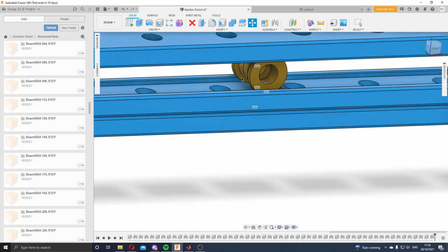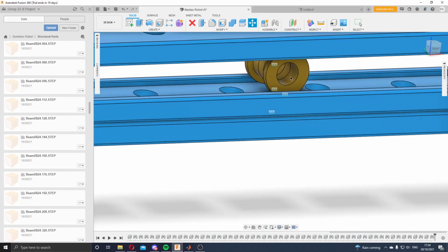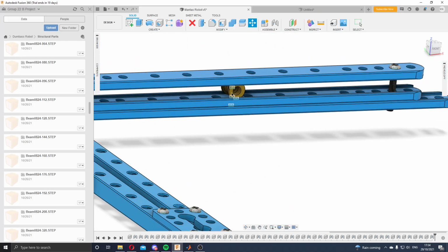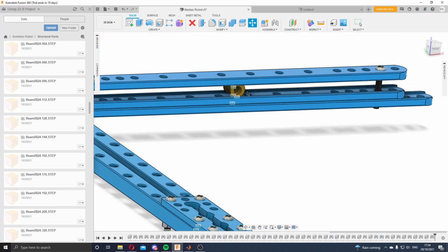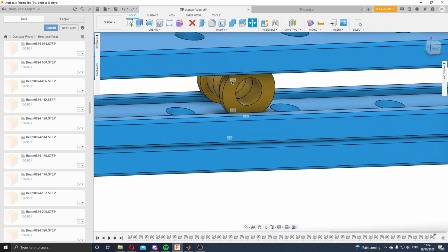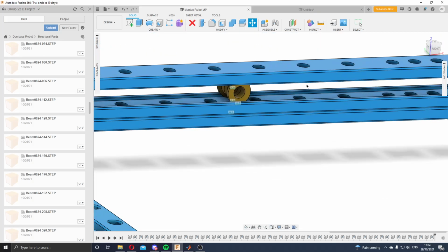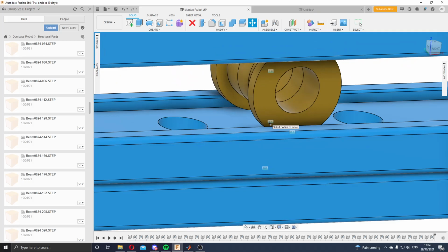If you don't want it to do that, there are these little things here, which allows you to select which bodies you are gonna move. So you can actually detach these bodies, for example. So in my design here, I have a little roller wheel that moves left and right. And if I selected this in this current state now, and I moved it, it would move along with the whole assembly. But, usually, if you click on this, it allows you to select which bodies to move.